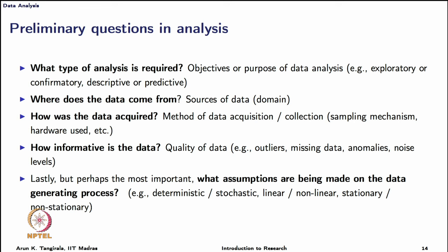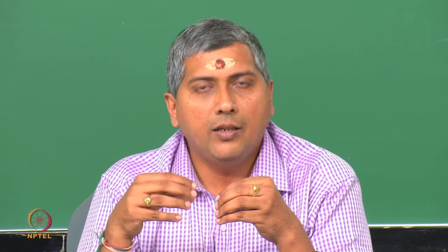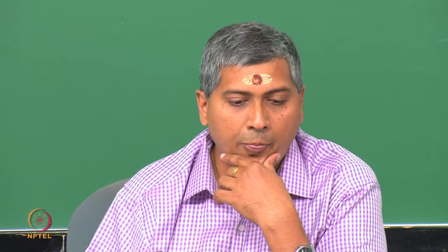Should be clear. You may be wrong in the beginning. We may make wrong assumptions. We may assume a stochastic process to be deterministic. We may assume a nonlinear process to be linear, a steady state process to be dynamic, and so on. It is possible, but we should stick to the assumptions that we have made throughout the data analysis, and be consistent and commensurate. That is, we should choose the right tools and so on, so that if we have made a mistake, in the end we do know that we have made a mistake, and then we go back and make corrections.